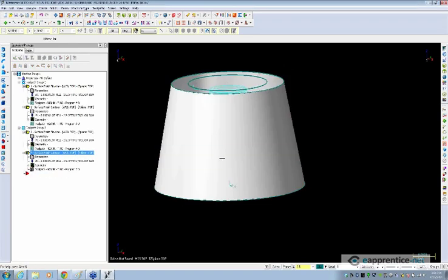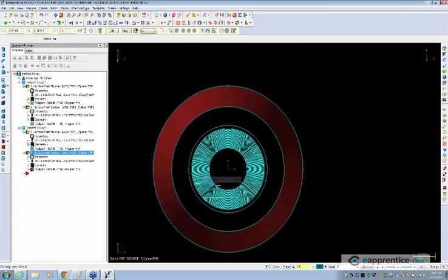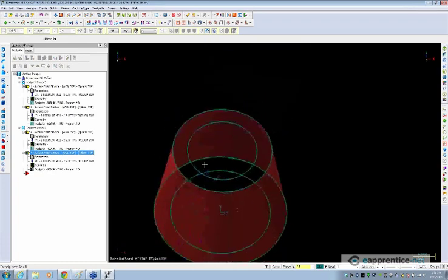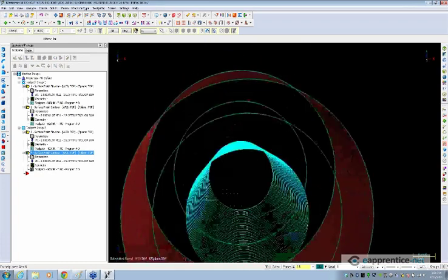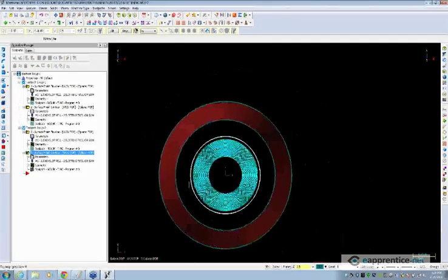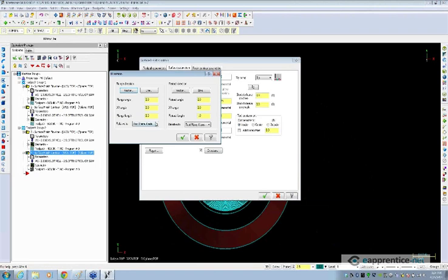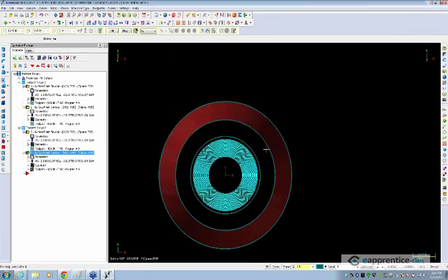So we'll regenerate that, and if we look at it from the top view, there's our entry motion. So it's coming in right here. We don't want that. We want it to come more from the center, so we're going to have to adjust that angle. Now, one of the things that I'll tend to do sometimes is I'll use a long plunge length just to be able to see where that plunge length is easily. So here's 3-inch, 3-inch. I wouldn't use that for the actual toolpath.